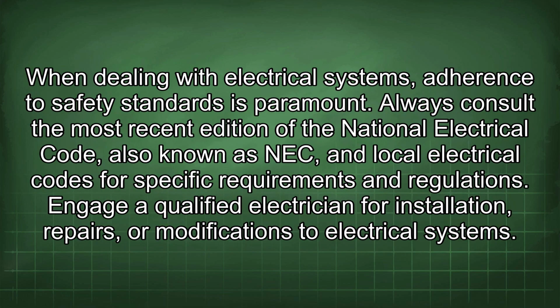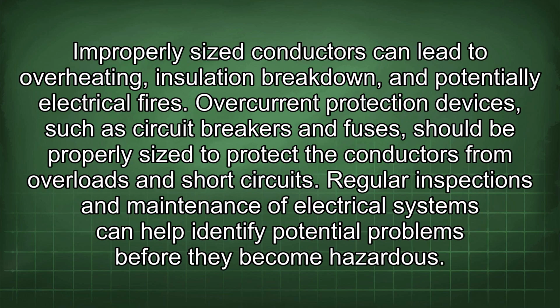When dealing with electrical systems, adherence to safety standards is paramount. Always consult the most recent edition of the National Electrical Code, also known as NEC, and local electrical codes for specific requirements and regulations. Engage a qualified electrician for installation, repairs, or modifications to electrical systems. Improperly sized conductors can lead to overheating, insulation breakdown, and potentially electrical fires.